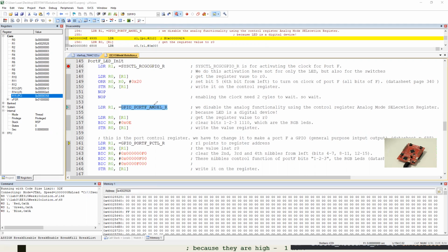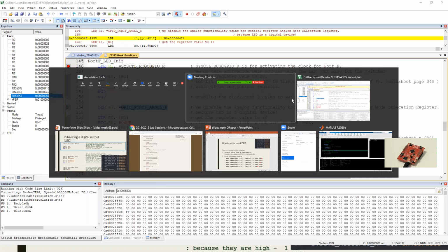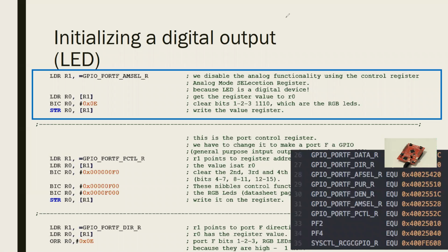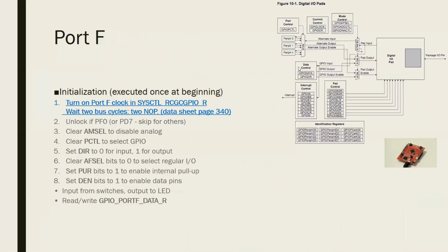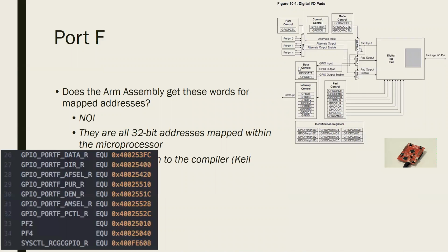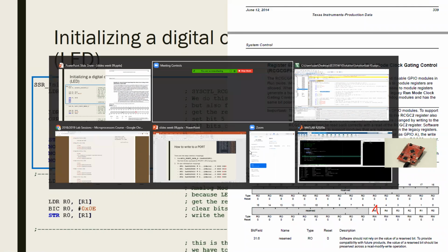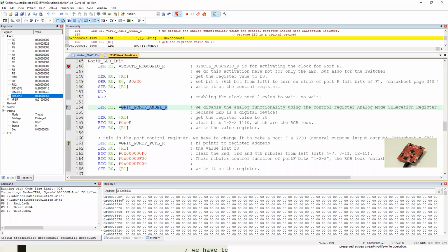Since these registers are 32 bits, although some bits are reserved, if you remember the data sheet, they are defined as 32 bits. All of the control registers are 32 bits. When I'm watching the memory, I'm checking all these 4 bytes because 32 bits correspond to 4 bytes.